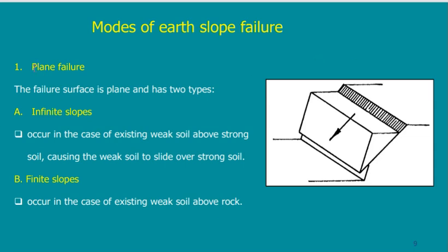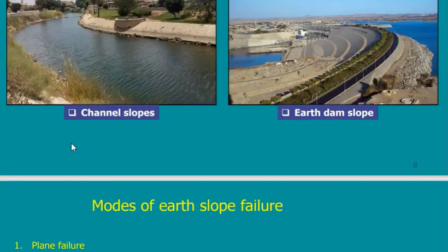So here, plane of failure. Plane of failure means where the failure is going to happen. Is it going to happen at this location or below? Is it a straight line? Is it curved? Is it 2 lines? I don't know. I have to assume. So it is, first of all, the plane of failure. Is it infinite slope or finite slope? Infinite slope, I will show you something.